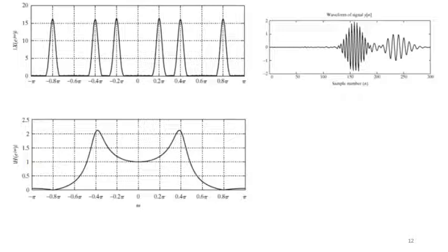From the filter frequency response, we see that the frequency group centered and concentrated around 0.2 pi, that is centered around 0.2 pi, will have a slight amplitude gain, whereas those at around 0.4 pi, if you can see, have higher amplitude here, right?